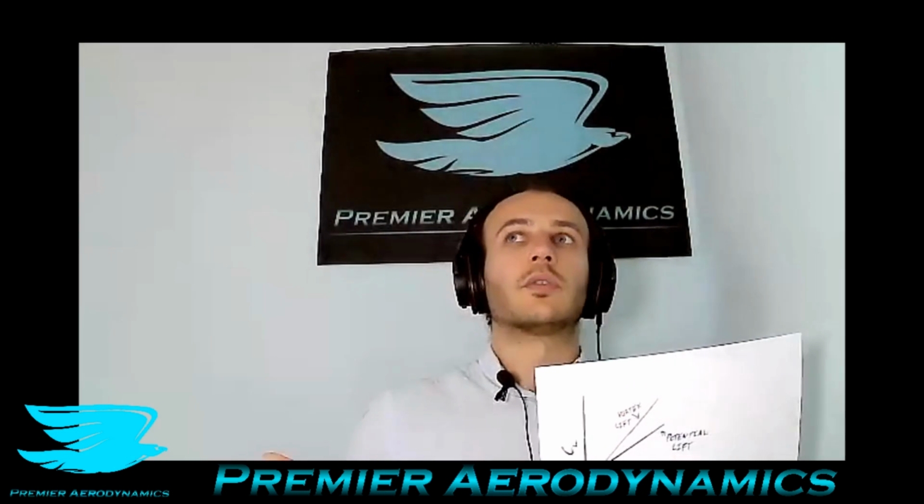Well, it is quite interesting, where in order for the delta wing to stall, you actually need to have something called a vortex breakdown. So the vortex over the actual delta wing just breaks up. It bursts, is what we call it. So it's no longer a coherent vortex core on either side with flow going over it. It just bursts, and that way you don't have this low core pressure region, which is sucking the rest of the flow onto the suction side. And then you start to get stall.